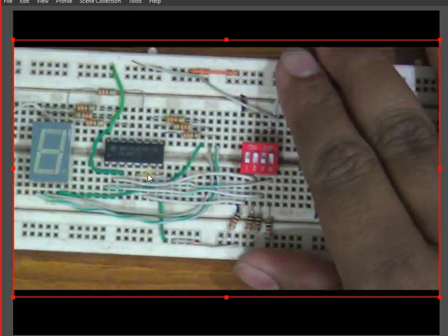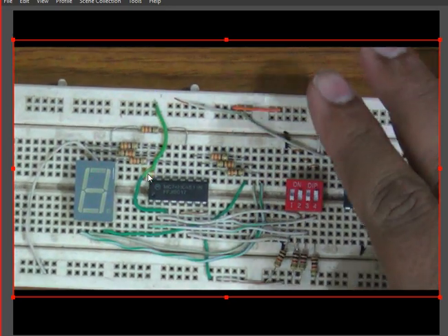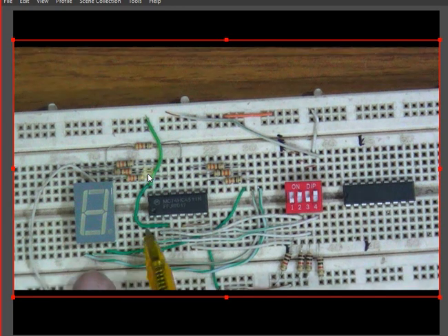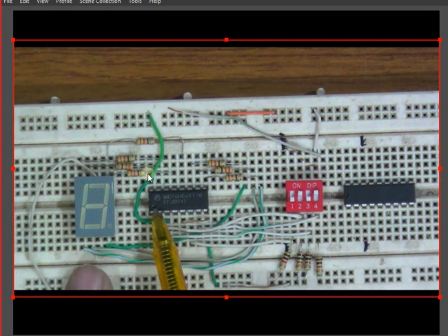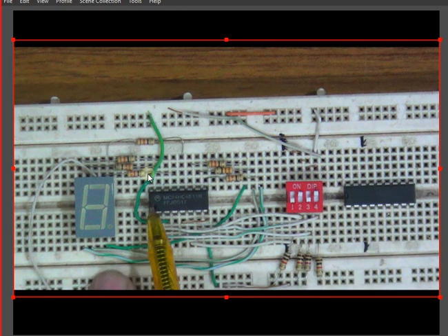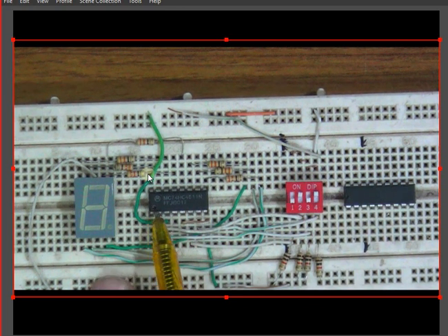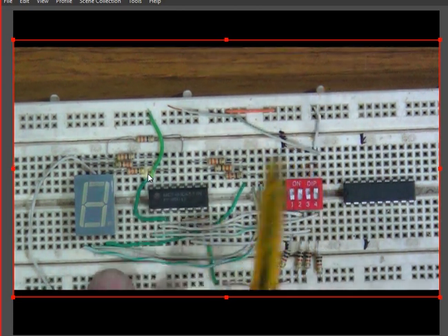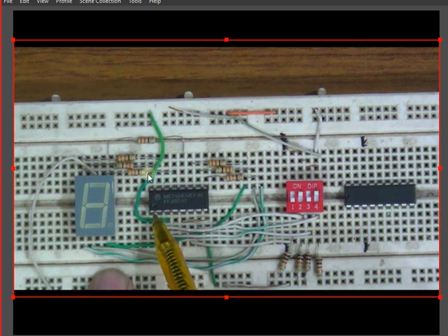You can see either there is a notch or there is a dot. On this IC there is a notch. On this IC there is not a notch; in fact, if you zoom in a little more, you can see a slight notch, but over here they have put a small dot mark. It's actually an embossed thing. So this means this is facing towards you.